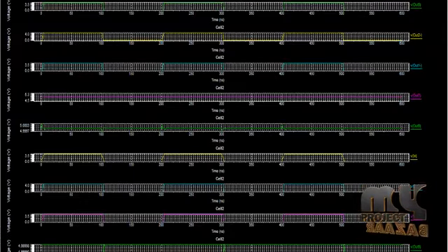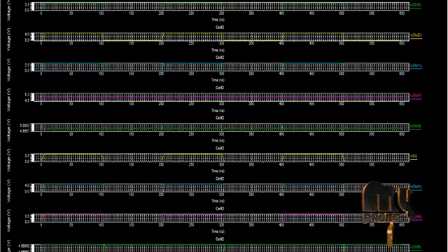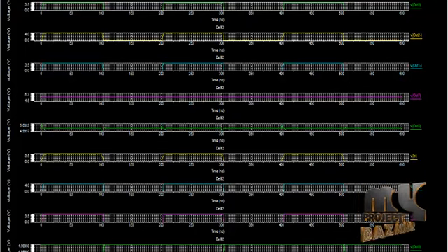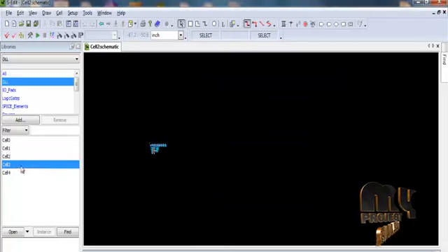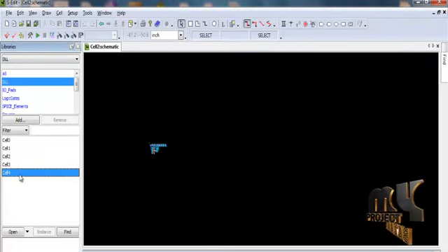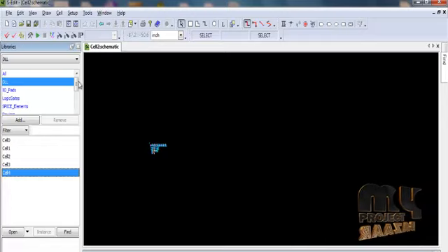These are the outputs of the multiplication ratio control logic. They are differentiated as positive and negative outputs. The negative output is denoted by the minus symbol, and the positive output is denoted by the plus symbol. This positive and negative edge trigger output will be overlapped. This overlap will be cancelled by the next cell. Cell 3 is the overlap cancellation, and cell 4 is the final buffer output.